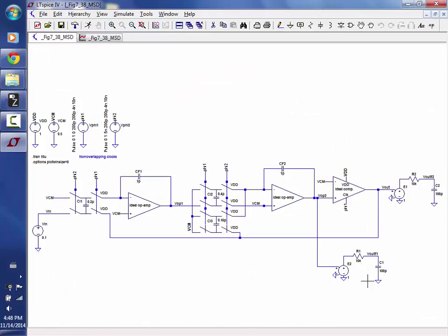And let me also comment that when you're looking at stability of modulators, which I'm going to talk a little bit more about in a moment, this technique of looking at the average is really useful because it gives you an idea for what value we used when we did our gain calculations. What was the variable name? What do we represent the gain of the comparator as? GC. Remember when we put the GC in, we placed it in series with the input of the comparator or output of the comparator.